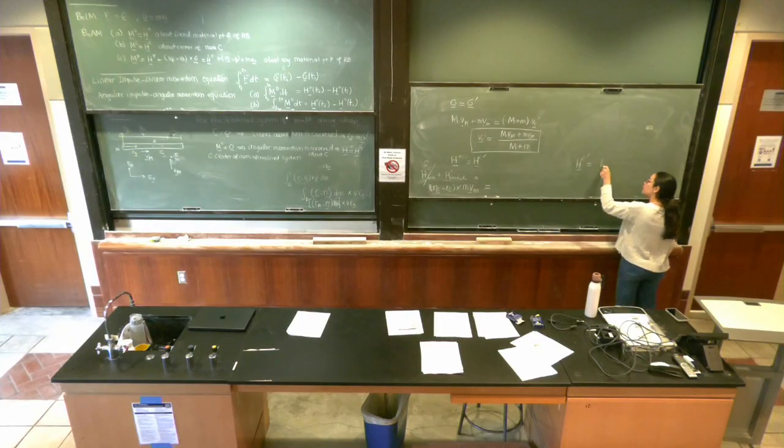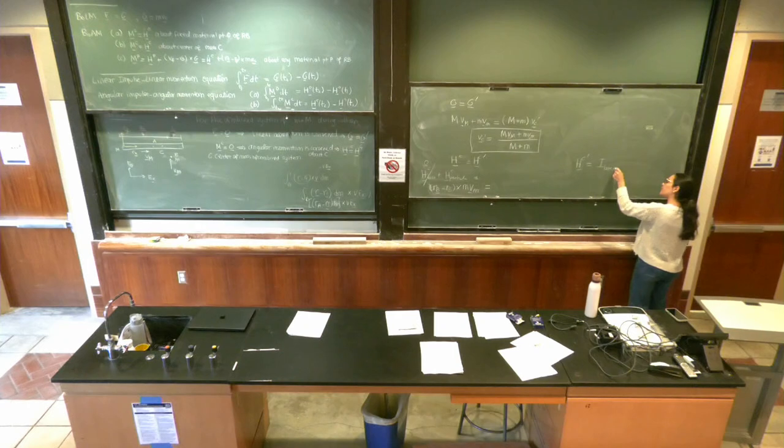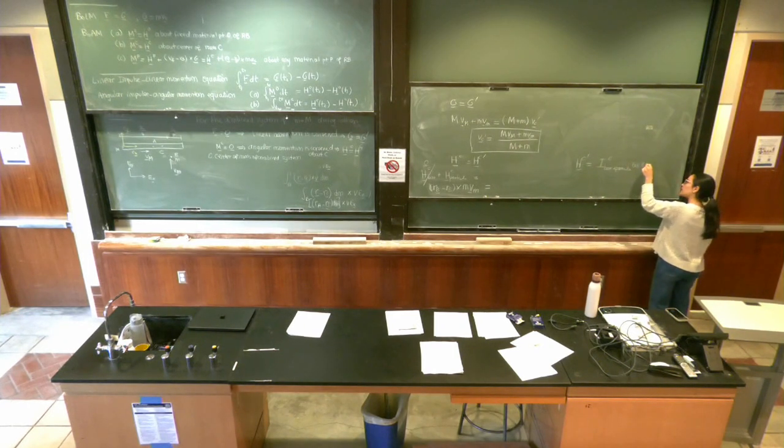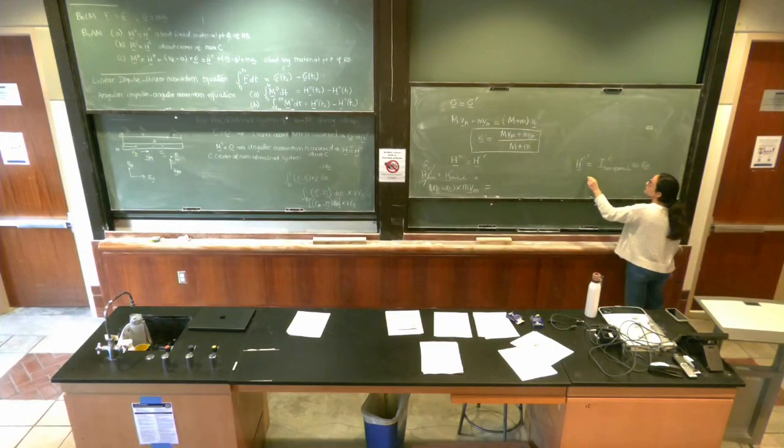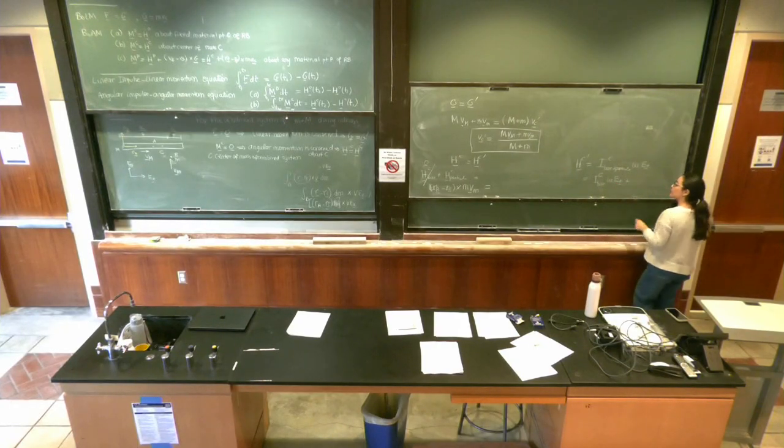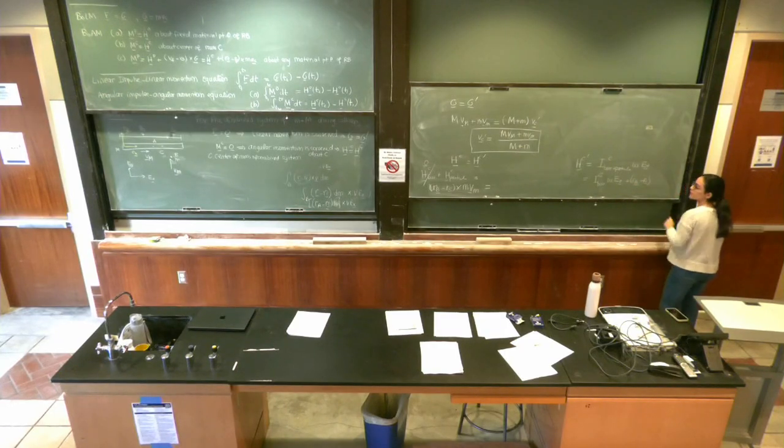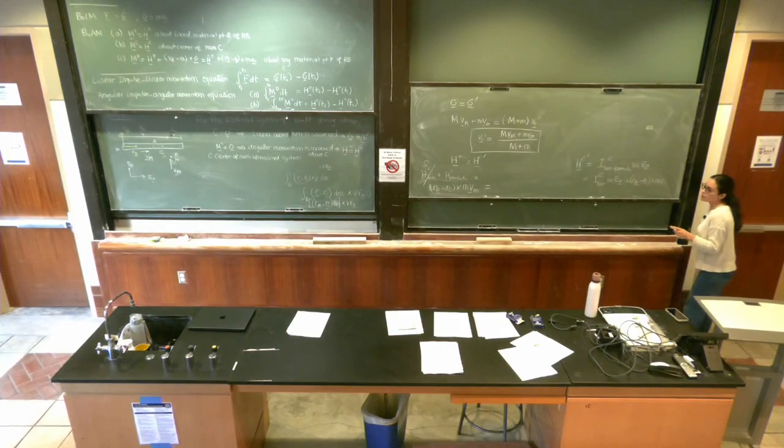I can think of a new moment of inertia of the bar plus particle about C, times omega Ez, or I can think about it as IC of the bar omega Ez plus RB minus RC of the particle cross m V of the particle, which is going to be now VB prime.